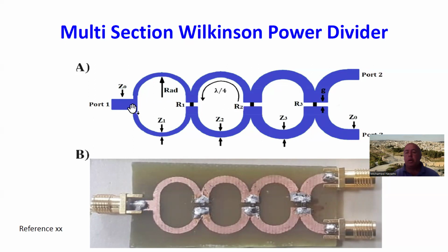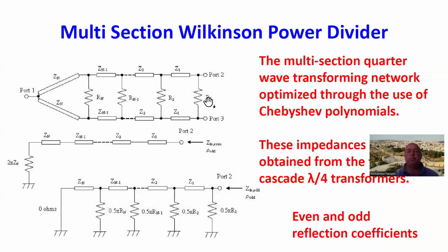And so for the design of this, when you go to the layout, you start out with an arc that goes from the middle of the 50 ohm in here up to here, that is 90 degrees. So you specify the radius and the angle of this, and you get that. Then you copy the same one and mirror image it in here. That gives you a complete semicircle that includes the back off, so you have a spacing for mounting this surface mount resistor in here, okay?